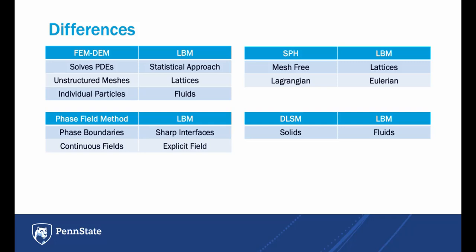The Lattice-Boltzmann method offers a unique kinetic-based approach to fluid simulation, standing apart from the continuum finite element method, the particle discrete element method, and smoothed particle hydrodynamics, or the interface-based phase field methods. It shines in complex multi-phase flows and parallel computing tasks, but trades adaptability for simplicity and lattice dependence.